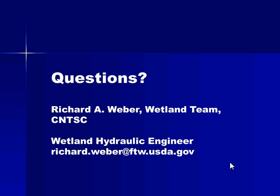How about any freeze-thaw type of situations that we need to be aware of or thinking about, Rich? Freeze-thaw is, I think of that more in terms of wetland structures and structure function. Ice effects on stop log structures or freeze-thaw effects on compaction of material in a saturated substrate.